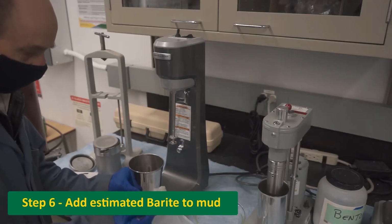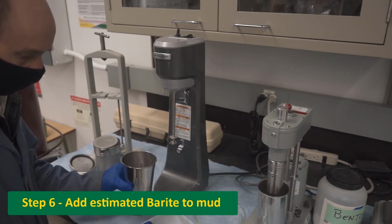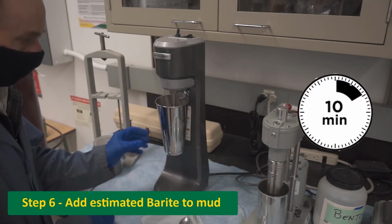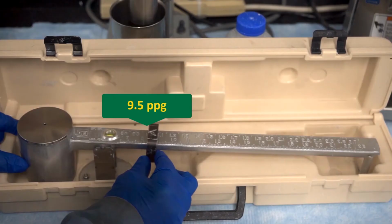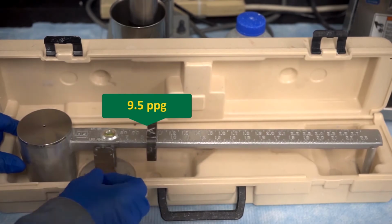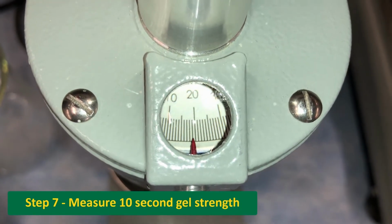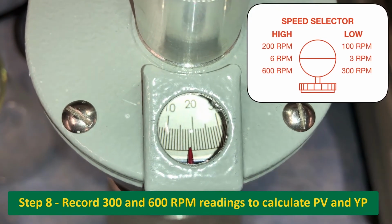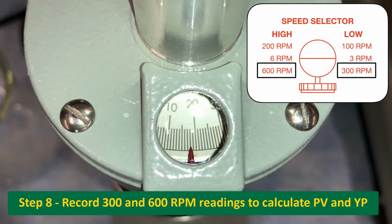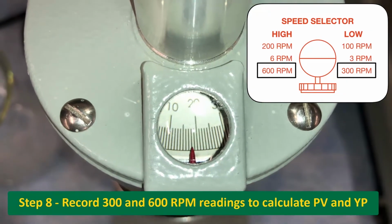Add the estimated barite to your mud, an entirely new sample. Mix for 10 minutes and measure the mud weight. The mud weight should be very close to 9.5 ppg. Now, measure the 10-second gel strength. Then record the 300 and 600 rpm viscometer readings to calculate PV and YP.